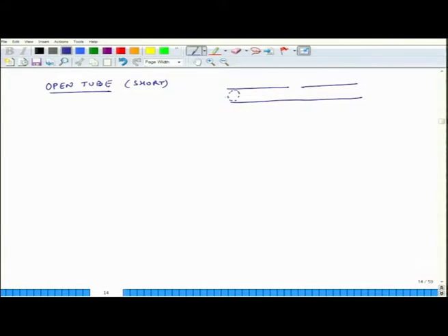and if this is the cross sectional area, and let us say the cross sectional area is S, then what I can do is attach an open tube on the side of it, and this open tube, which is not too long, actually it is a short tube, can also act as a resonator and it can kill a lot of noise associated with a particular frequency. So, if the diameter of this tube is 2a and the length of this tube is L, then I am going to again directly write the results.